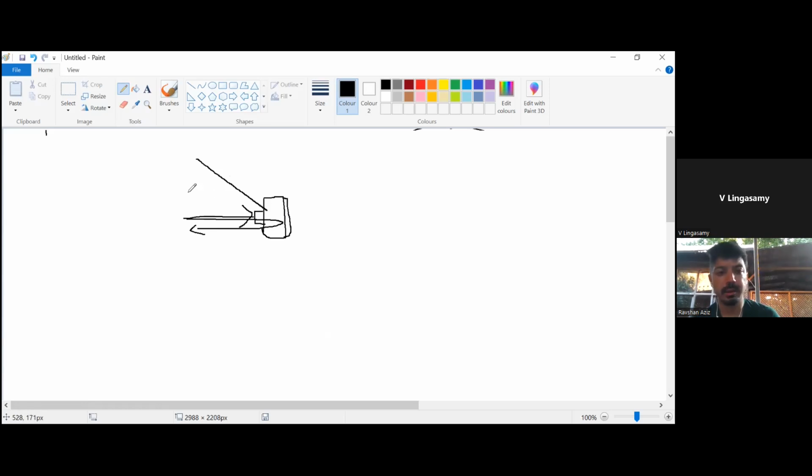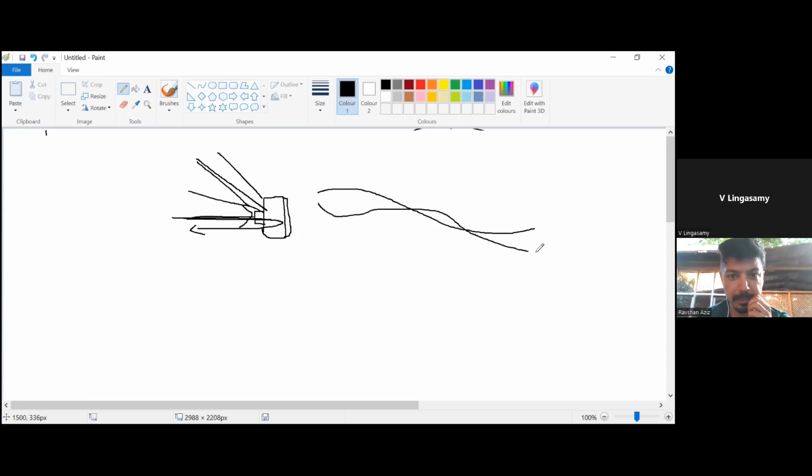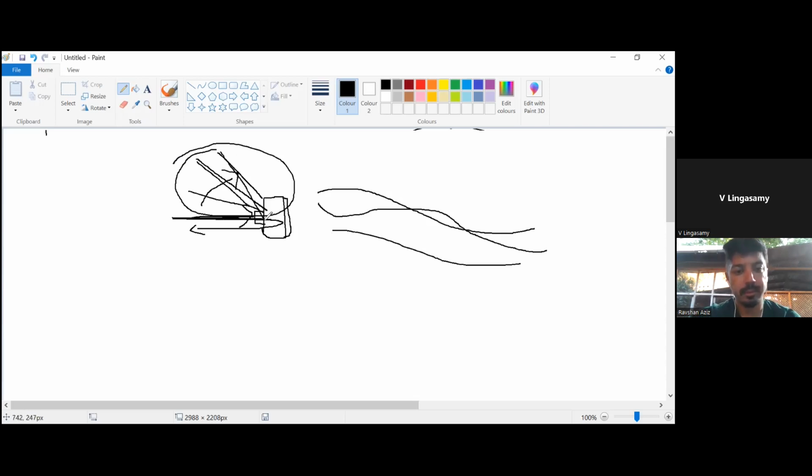When you start increasing the angle of incidence, then you will see the phase variations. For example, for this curve you are getting an S curve. For the broadside one you are going to get something like this also, or some kind of phase offset when you start moving away from broadside, with waves coming from different angles. So for your application it is very important. Even if the angle of incidence is, for example, 40°, you still need to get approximately this.